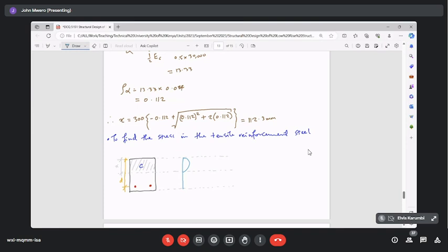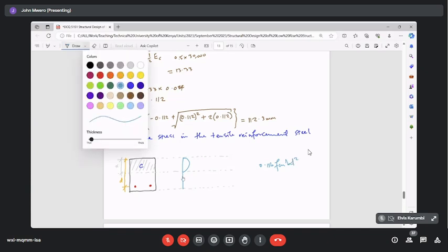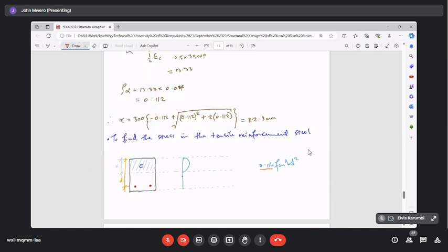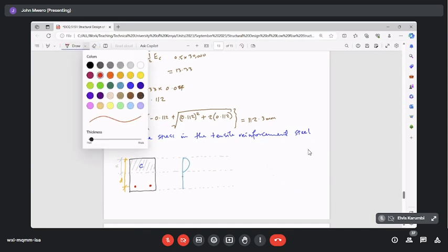And that is part of the reason why things like this equation here, which you must have come across at some point, 0.156 fcu bd squared. The variation of this shape is what gives rise to the variations of that factor. For example, this is the BS. The Eurocode, I think, talks of 0.167 fcu bd squared. So these variations of this factor are basically because the stress distribution shape of the concrete in compression for a concrete element in bending has not been agreed upon universally. So most different standards will have a different description of that, and therefore this is reflected also in the design equations. But that is by the way.